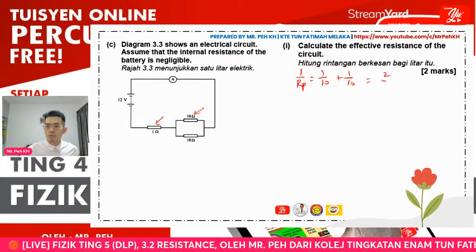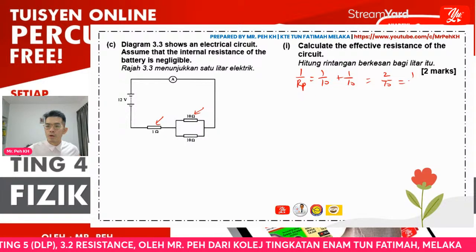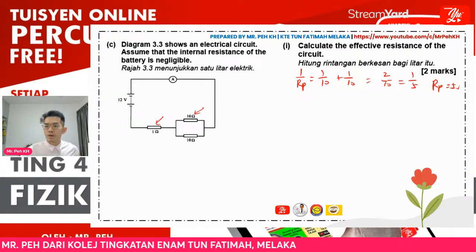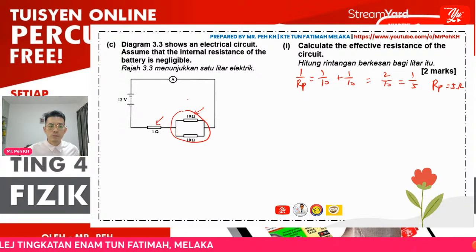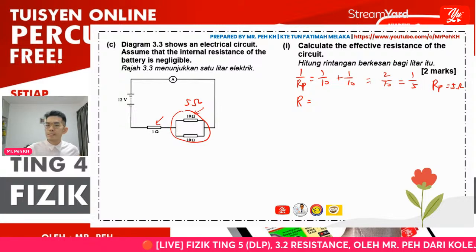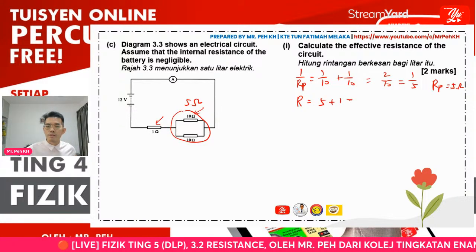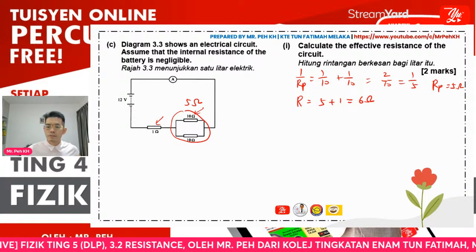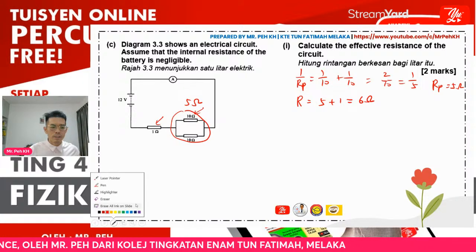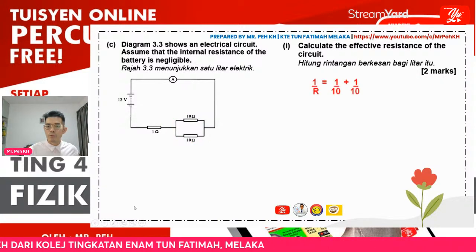Here we get 2 over 10, so it will be 1 over 5. So the parallel part will be 5 ohms. Then the total or effective resistance will be 5 plus 1, which is 6 ohms.